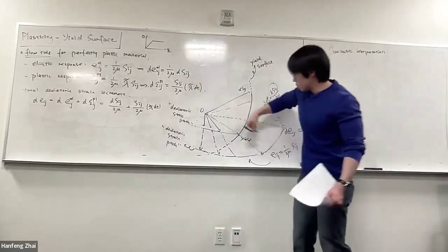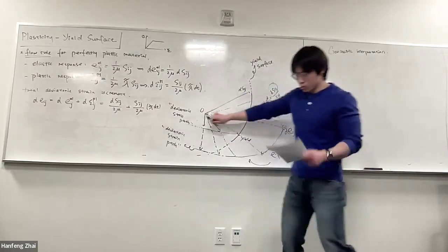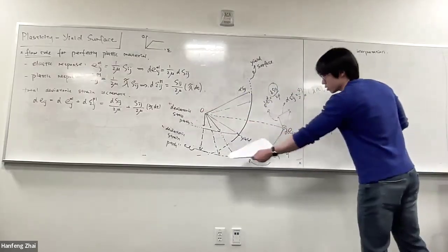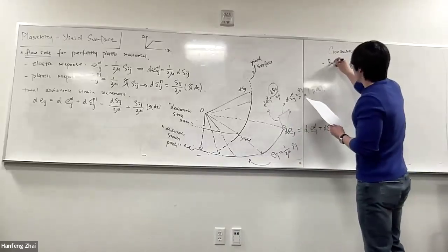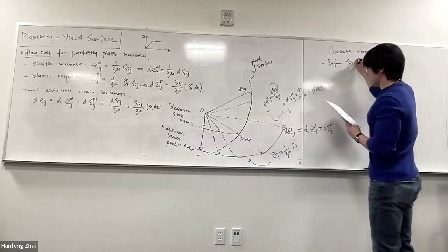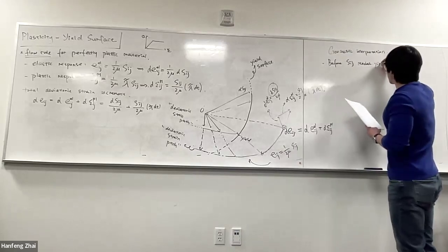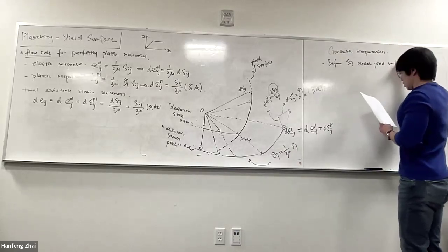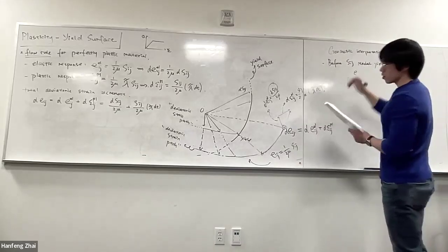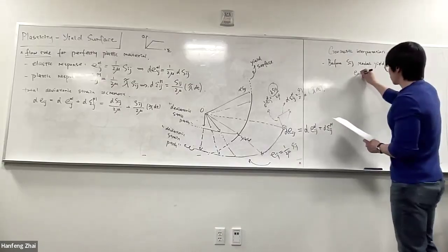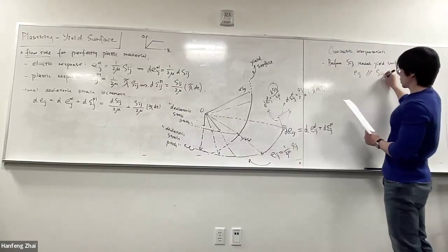So when you apply any stress following this deviatoric stress path, before S_ij reaches the yield surface, you are in the elastic regime, in which e_ij, the deviatoric strain, is parallel to S_ij, right?